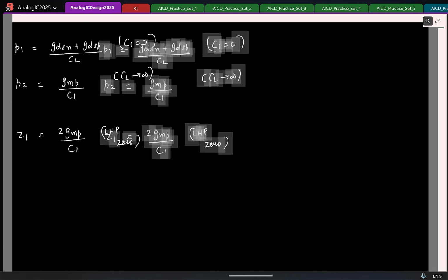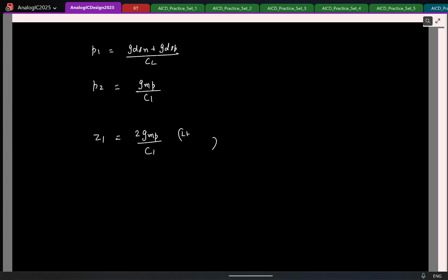Now couple of jargons to remember. So typically the low frequency pole is what we call the dominant pole. Have you heard this term before, dominant pole? Yes. Okay, why is it called dominant pole? Like this low frequency, it's near origin. Okay, so why should that be dominant? The transfer function can be approximated to this pole when there is a particular condition. Other poles are far away.